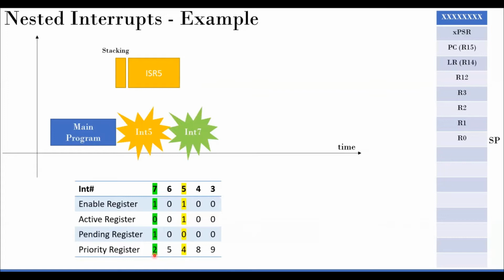So that happens, and what exactly happens is you do another stacking. Remember this, after this stacking, all these contents from the main program are already there. So R0 is the R0 of the main program, R1 is R1 of the main program, and so on. PC is the PC of the main program, whatever address here. Right? So now what happens? Oh my God. There's a problem here.